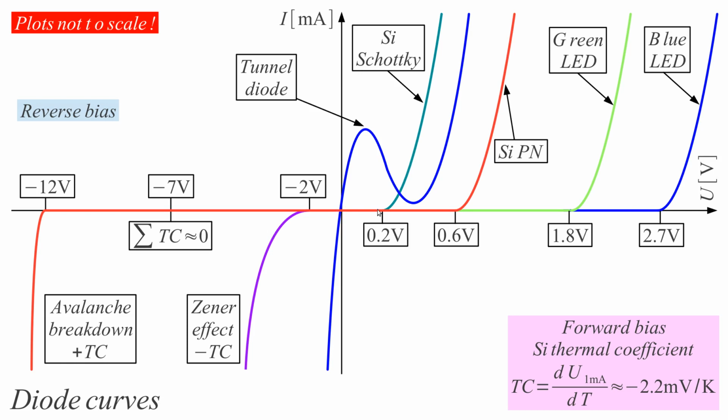The back diode is also a kind of tunnel diode, not used as a negative resistor like the true tunnel diode, but used as a high frequency detector, because the tunnel diode is usually operated in the tunnel region. In the tunnel region, we only have majority carriers. We do not have the charge storage of minority carriers that slows down PN junctions in the forward region.